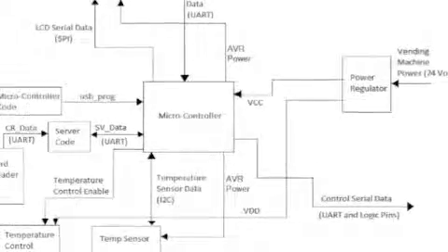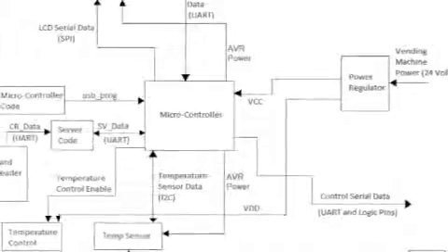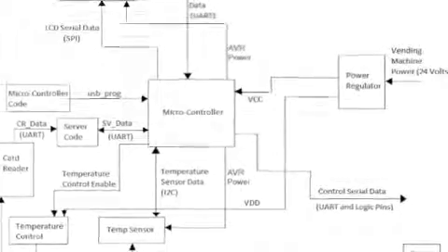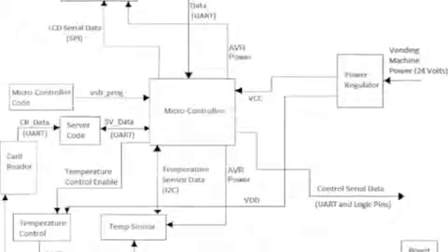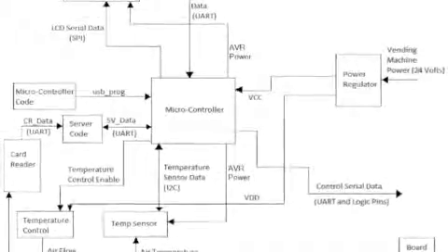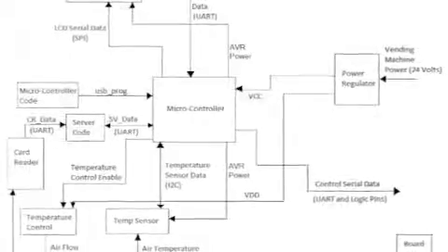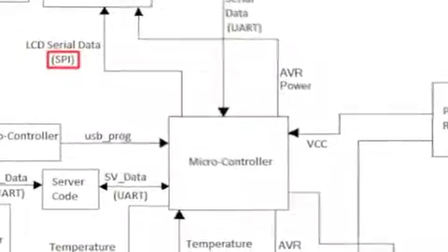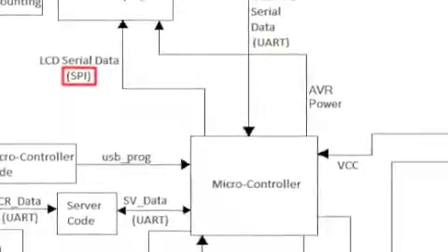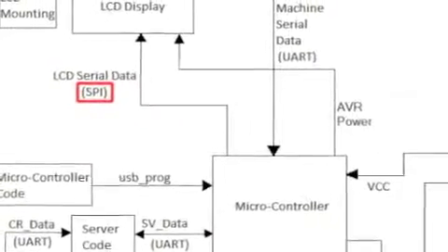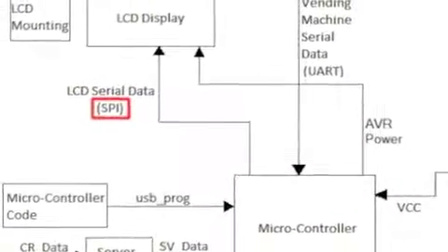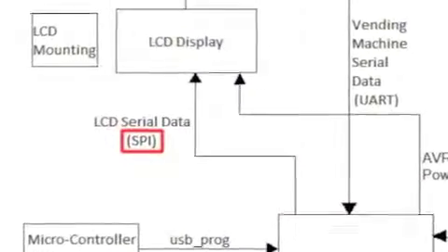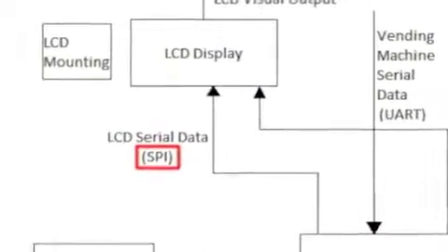We now move on to our top-level block diagram, which shows the relationships between all the individual component blocks in the top-level design. We begin with a brief description of our serial protocols, SPI, I2C, and UART. We utilize SPI to talk to our LCD. SPI uses 4 logic lanes to transfer data and can both transfer and receive data simultaneously. By checking a status register, we know when these processes are complete and can then utilize the data to perform specific functions within our blocks.